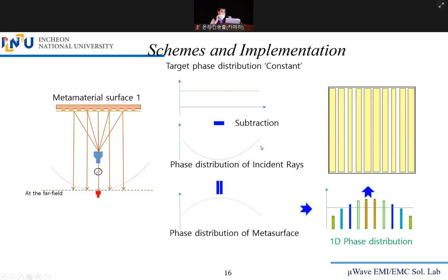So you can synthesize this. Can you see the metal strips on the FR4 or some dielectric substrate? These are the metal patterns on top of the dielectric material. Going through this direction, you can see do, re, mi, fa, sol, la, ti, do, like that. In this direction, these phases should be implemented by the width of the strips. Can you see the difference in the width?